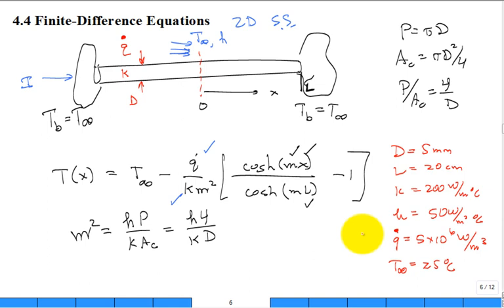But now let's solve this problem numerically. How would we solve this problem numerically? One of the first things you do is discretize. You introduce nodes, and you have regions identified with each node. So you can put a node right there, and you could put a node right there. That's 2 nodes, but we want more nodes because we're only going to get the temperature at nodes. We're not going to get the temperature at all locations. The analytic solution gives us the temperature at any x in our region. X goes between 0 and L. But now we're just going to go there.